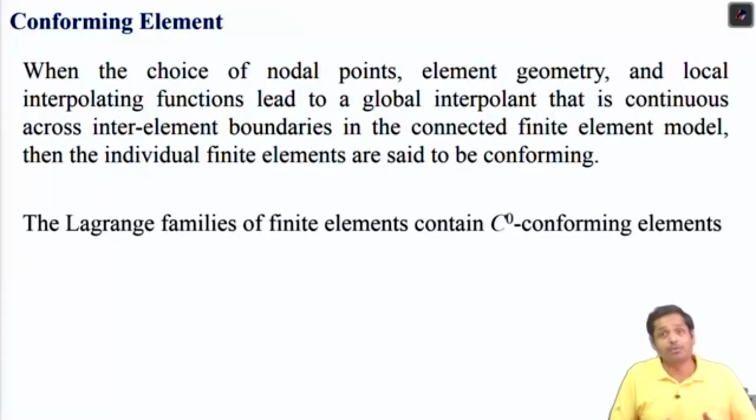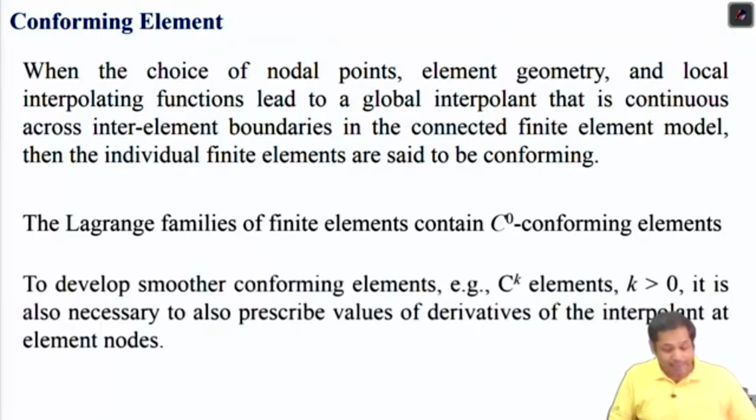There the slopes, the derivatives, are also interpolated. Suppose we want to analyze plates and shells problems, we will see that at the inter-element boundary it is not just the primary variable; we have to make the derivatives also continuous. That kind of element, where the order of continuity is higher, is necessary for some problems, and there the derivatives are also to be interpolated.